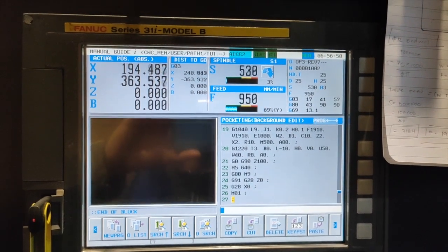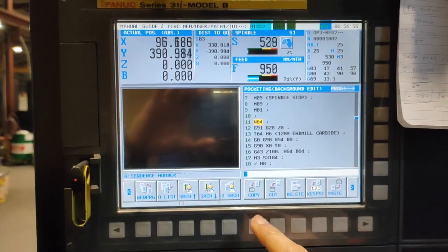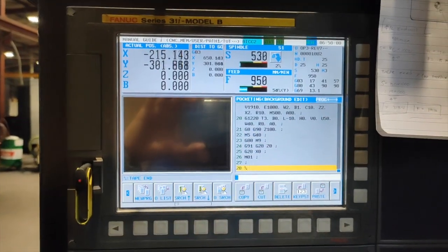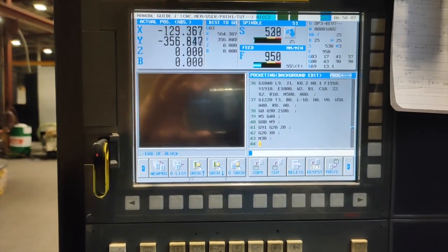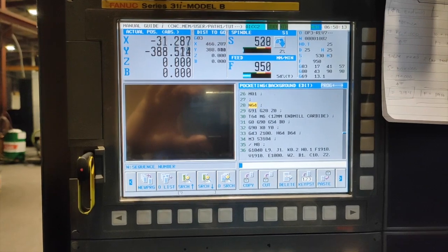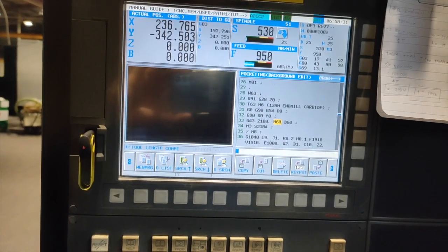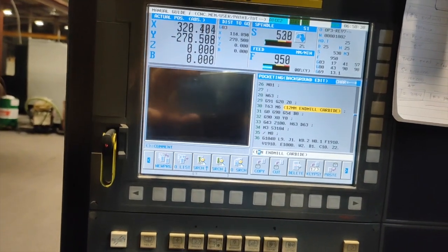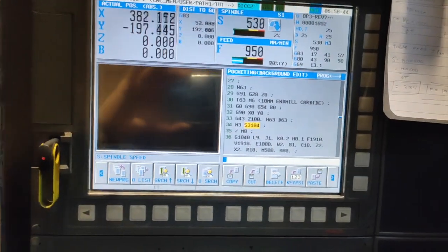Since we have our roughing pocketing, if we want to add a finishing tool, we can just copy this one, copy, and then we are just going to paste, make this one M30, and we delete this last end block, and then we are going to change it to D63, and we are going to alter this one to 10 mm, 10, and we need to change our spindle speed.